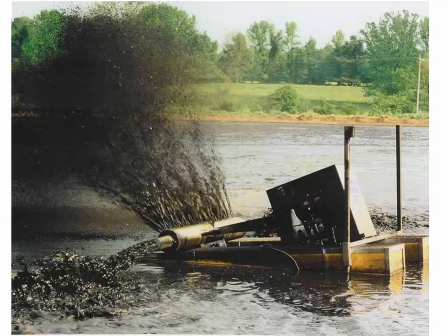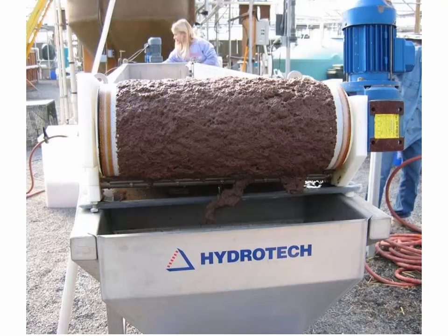We can do a little bit better than that, though. Not every place wants to have a big lake of sludge nearby, right? This is maybe the simplest thing to do, but an easier way to treat sludge, first of all, is to squeeze it with a belt. And this is a photo of, think about if you have a fabric belt that's progressively getting closer and closer together. If there's sludge in that fabric belt, by squeezing it, the water will drain down through the fabric, and then the solids stay together, and it goes over the edge and into a hopper that collects the solids. And this can be very effective at removing the water from the sludge.